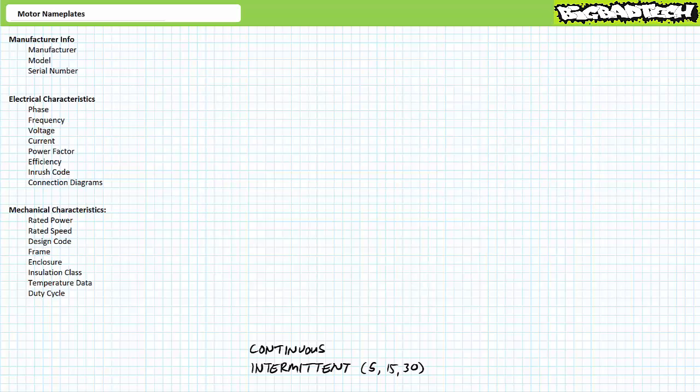Alright, that about concludes our brief tour of the most important manufacturer, electrical, and mechanical entries on a motor nameplate. As I mentioned previously, not all motor nameplates include all data, nor are they formatted identically. Additionally, motor nameplates may include accessory information, like service factor, which is kind of like a multiplier to a motor's permissible power rating, meaning it can be operated at a degree above the rated value without suffering damage. Electrical characteristics at service factor and/or mechanical information like bearings or lubrication might also be printed on a motor nameplate. Despite the variance in forms and entries, you should be able to interpret important manufacturer, electrical, and mechanical entries at the rated conditions for most purposes. We'll examine electrical and mechanical properties at other than the rated conditions in later lectures.